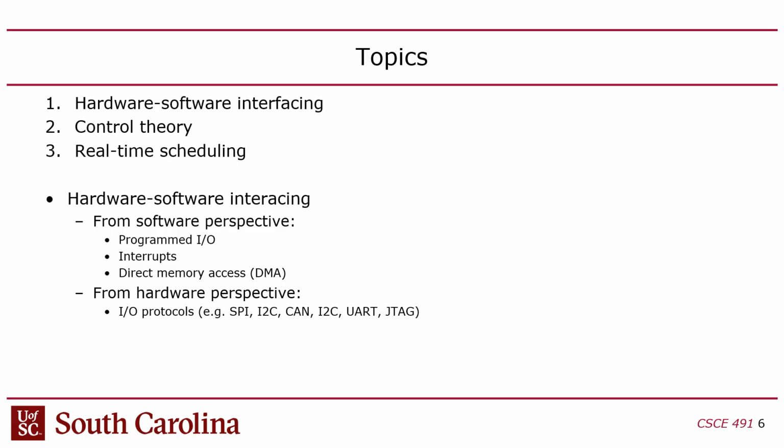but after that point, the CPU then has to go and do these I/O transactions, loads and stores, right? And finally, there's a third mechanism called direct memory access, DMA, which is for high-speed peripherals, where the CPU has another chip that does bulk data transfer on its behalf. Because when you have to load and store, you can't do that at a very high speed. Your effective rate is very low, by having the CPU shuttle things through load and store instructions. Okay, so we'll talk about that stuff. That's a big topic that we want to address.